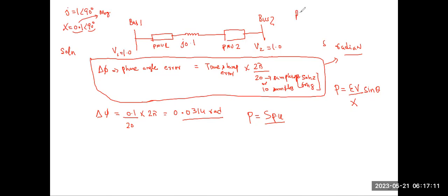Yesterday I explained that per unit means the actual value divided by the base value. Why is it done? To make a common currency, because the transmission line, voltage, currents, P and Q all have different units. Addition, division and multiplication of those values becomes difficult, so we keep a common currency. Per unit is just like a dollar.